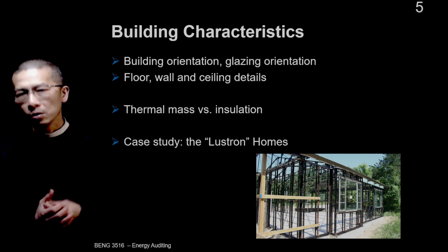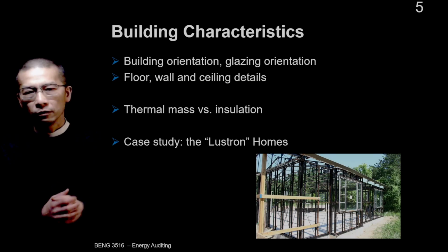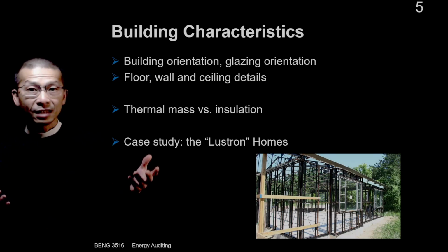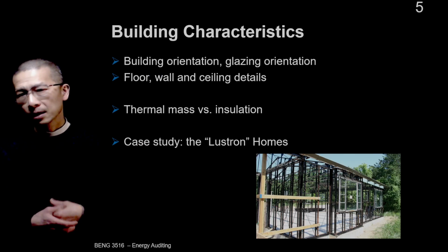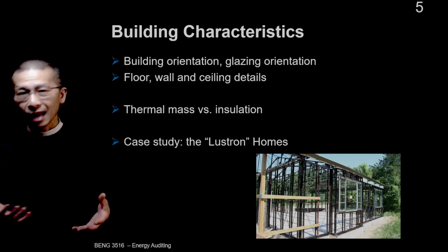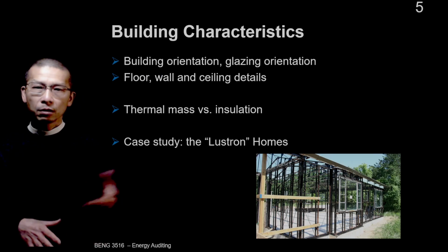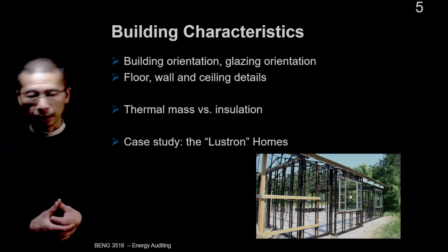We need to know if it's a flat roof, a pitch roof, or a drop ceiling with unconditioned plenum above it. Floors: is it a slab on grade where heat is lost to earth, or is it over a ventilated crawl space, right?